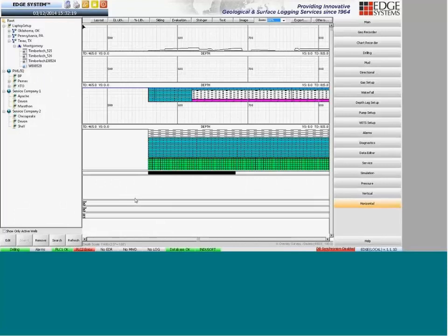So we do not require any more inbound connections from the server to each one of the remote well sites. Each one of the well sites makes an outbound connection to the central server and pushes data to the server. So it helped us avoid having to do any kind of customizations on the security settings of each site to allow inbound connection from the server to each one of the sites.